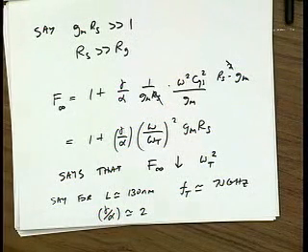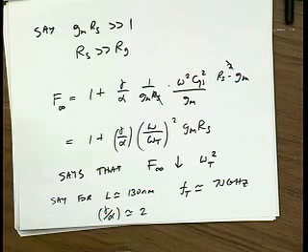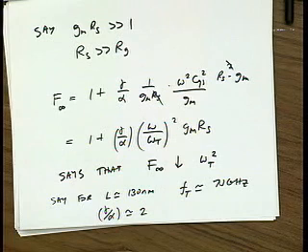And automatically we didn't have to worry about correlations because we assumed that all the noise sources in the transistor were uncorrelated. Now if you've been paying attention, you might say, you made a mistake, because in fact the gate noise has a component that's correlated to the drain current noise, right? That's in fact true. It turns out though that if you take that correlation into account, sure, you'll get a more precise answer. But I found that even if you ignore that correlation and you're doing some back of the envelope calculations, you still get a pretty good match to the real value.